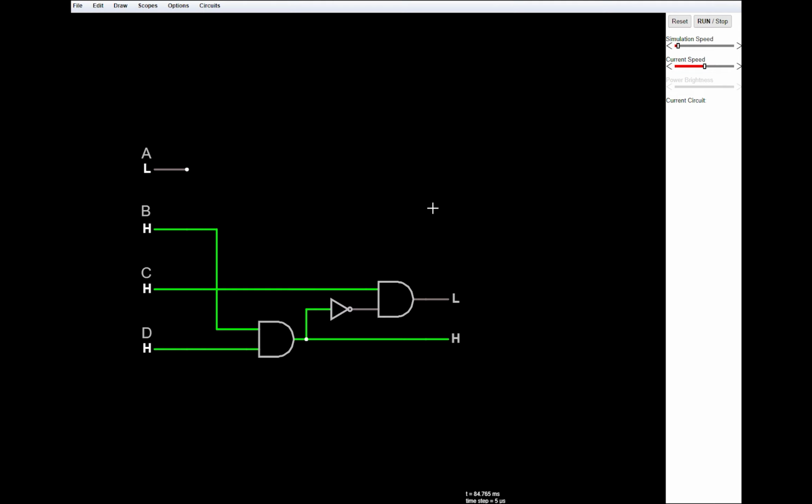Gate delay refers to the simple fact that logic does not happen instantly. It takes time for the outputs of the AND and NOT gate to switch, in this case around 10 microseconds. In this case it doesn't really affect anything, but what if I made the assumption that both of the outputs would never be high at the same time? Or if I connected my circuit to another circuit where the output changed depending on if output 1 or 2 was reached first. That is what we call a race condition and will be the subject of a future video.